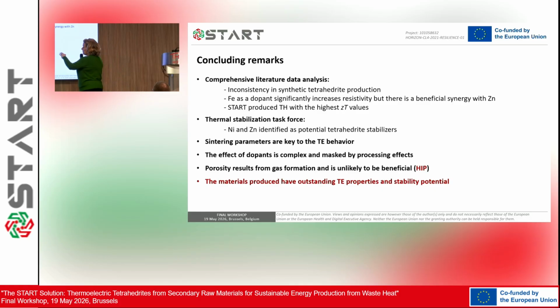Nickel and zinc have been identified as potential stabilizers, so it might be that iron and zinc are what we want, but maybe we want to add a little bit of nickel or a little bit of zinc, or maybe even a little bit of chromium, depending on how much we can dissolve, because that stabilizes in terms of temperatures.